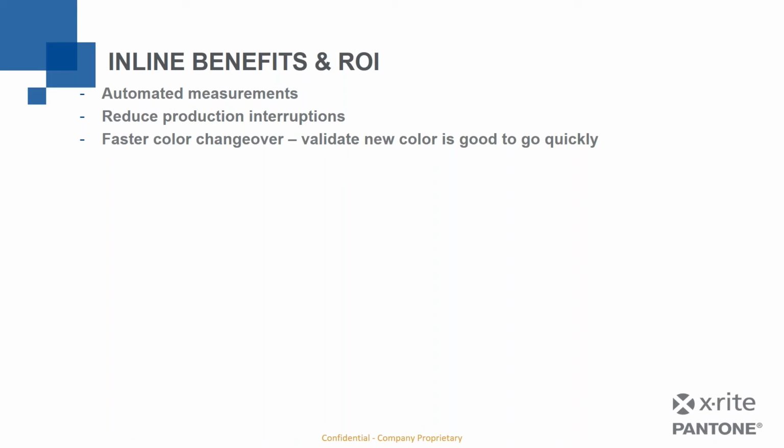I'm switching over to the second color. I'll know when I need to cut off because now I'm starting to get color that's off because of the changeover. I get to the new color. I'll know immediately when that new batch has reached the color that I'm trying to achieve, and off I go. And so I eliminate how much waste I have, waste of time and material in color changeover, because I'll know when to stop and when to start calling my color good.